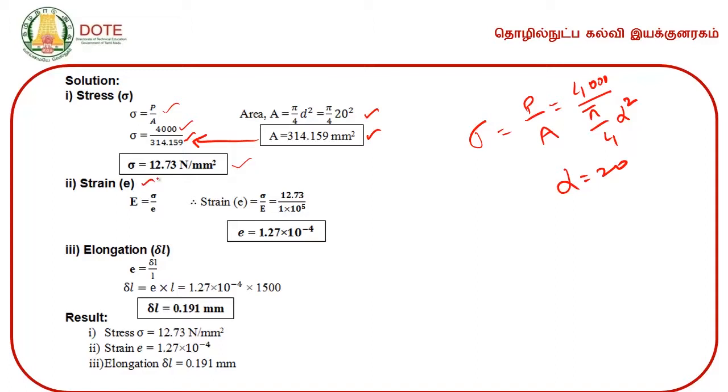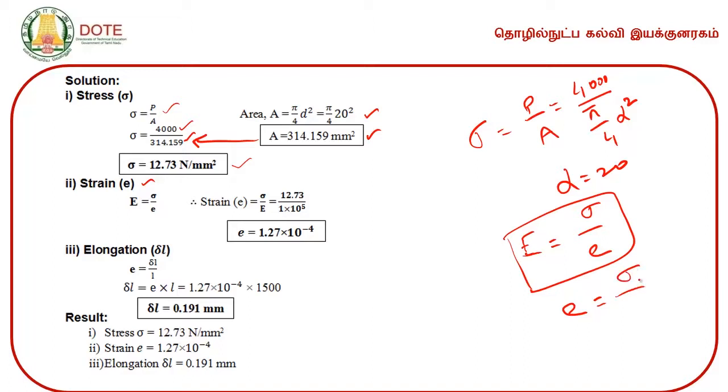What is strain? How to find the value of strain? We know that Young's modulus E is given by stress by strain within the elastic limit. Young's modulus E is defined as the ratio of stress to strain within the elastic limit. So from this we can determine the strain. Strain is sigma by Young's modulus, because Young's modulus is given in the problem as 1 into 10 to the power 5 Newton per mm square, and sigma is the stress value just now we have determined.